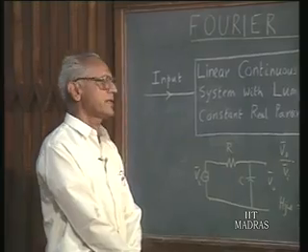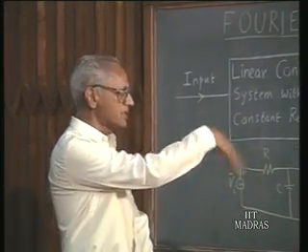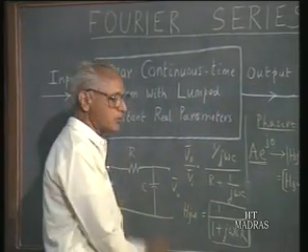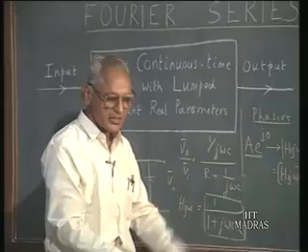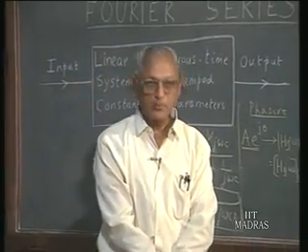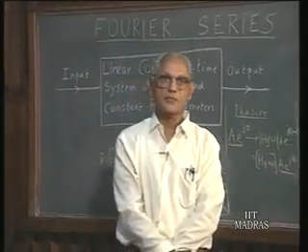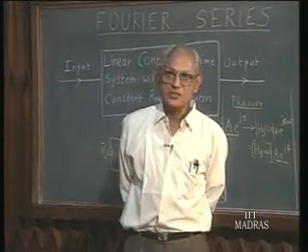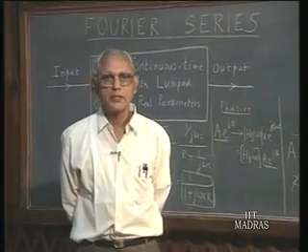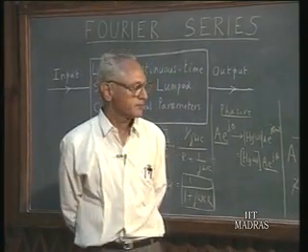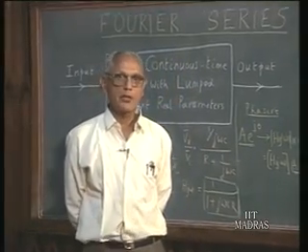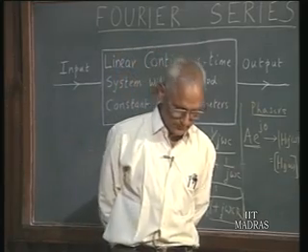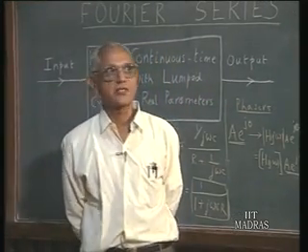Now, we understand here, of course, that when we talk about the output in the entire discussion here, we are talking about the particular integral solution. Suppose you have an input, when we talk about H of s system function and so on, normally the output is the particular integral solution. In the case of AC signals, sinusoidal signals, the common systems, the complementary solution gives rise to decaying transients, and therefore the particular integral solution is what remains forever. It is the steady state solution. The complementary solution is a transient process.